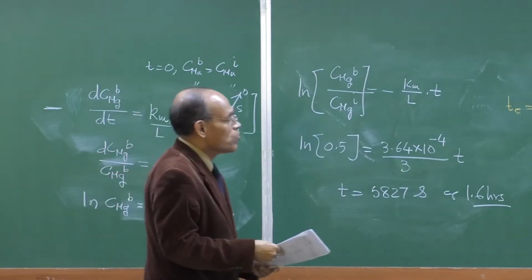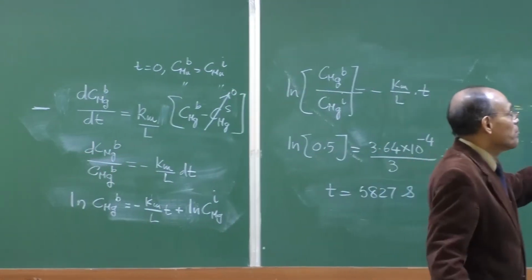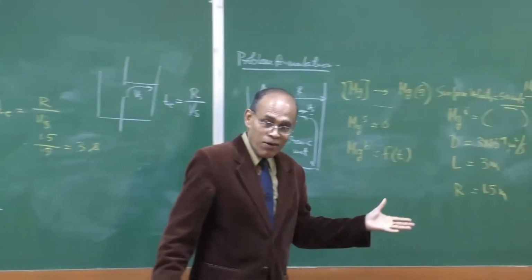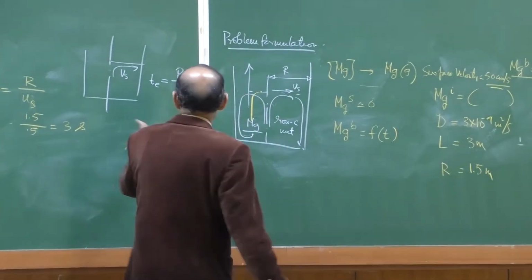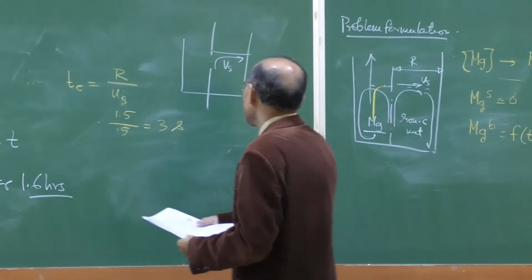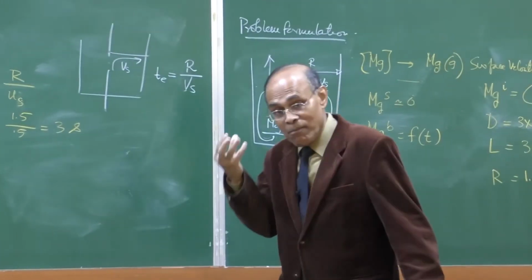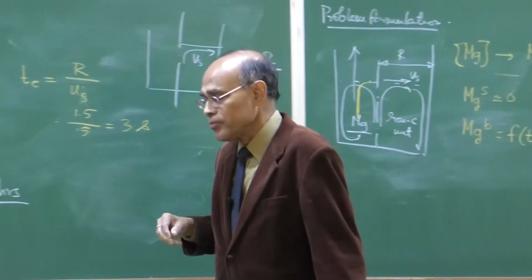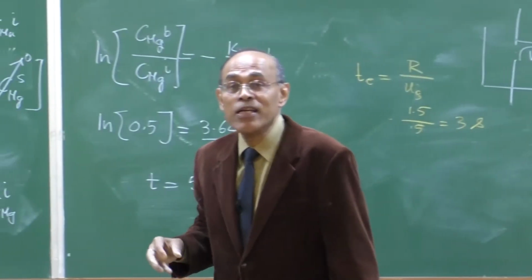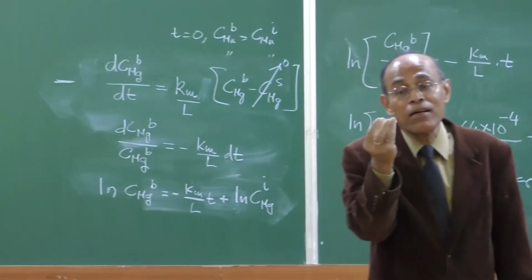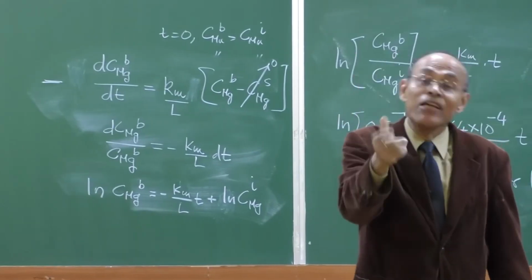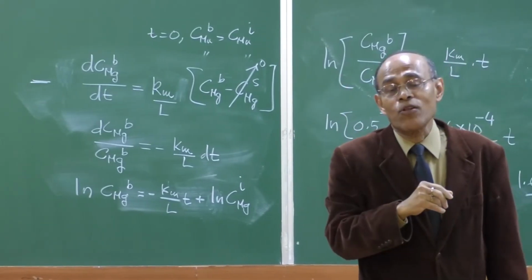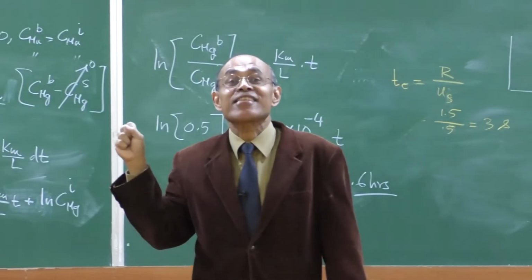This is basically applicable to laminar flow systems. So, using the Higbie penetration model, you can find out, for example, bubble to liquid mass transfer. If you assume a liquid droplet settling or rising, you can also find the corresponding mass transfer rates, corresponding extraction rates.